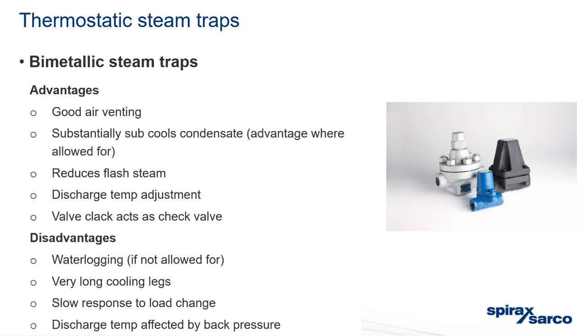Yeah, and also just to add to that, as the question says, what about vertical distance or vertical direction changes? Absolutely, every time you have a vertical direction change, this is an ideal opportunity to remove a lot of condensate, especially after shutdown and so on. Those are also ideal places to add air vents at the top of that end of line arrangement.